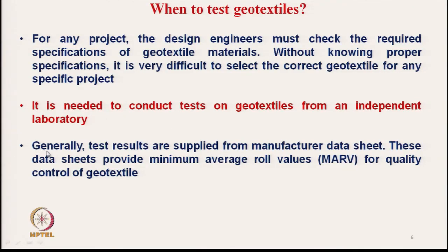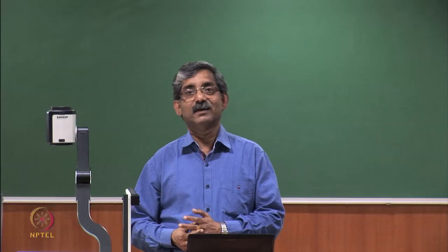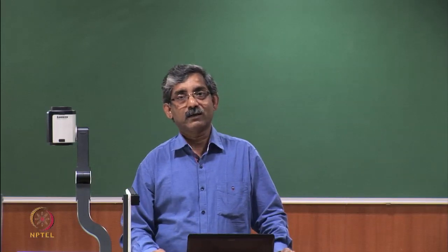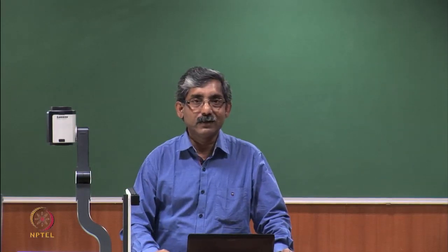Generally, test results are supplied from the manufacturer. This data sheet provide minimum average roll value MARV for quality control only, but actual test data we have to get from an independent laboratory.